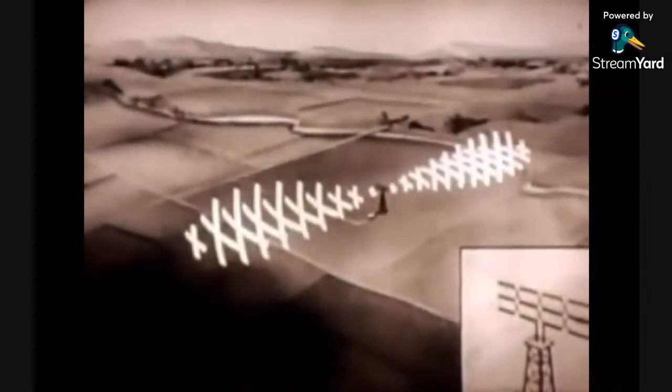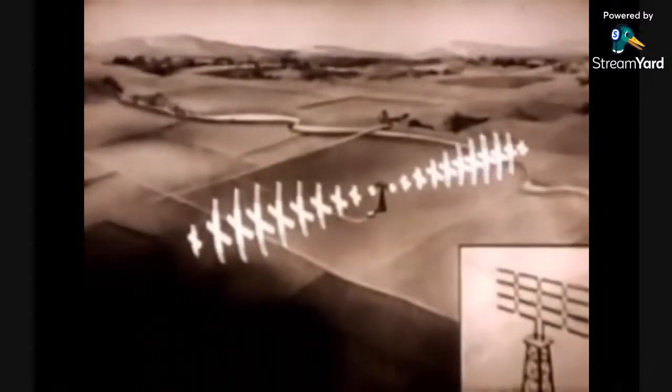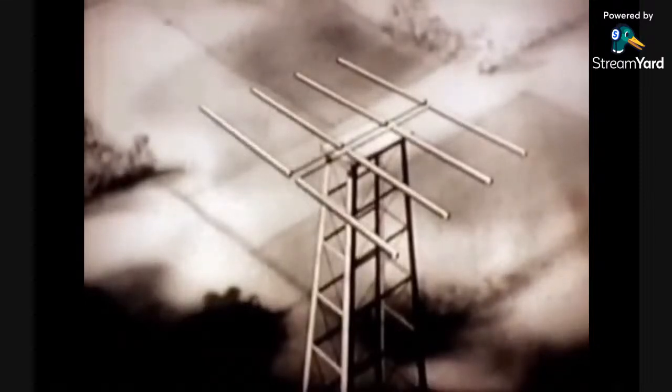Returning to our antenna patterns, there are several ways of obtaining sharp control, both horizontally and vertically. The end-fire array antenna is one of them. Physically, the end-fire array resembles a broadside array laid on its side. There are several rows of elements, one behind the other, but operationally there is no resemblance. Each row of half-wave elements is energized out of phase with the next row. With such energizing, the wave pattern is compressed and channelized. Maximum wave radiation is sent in two directions.